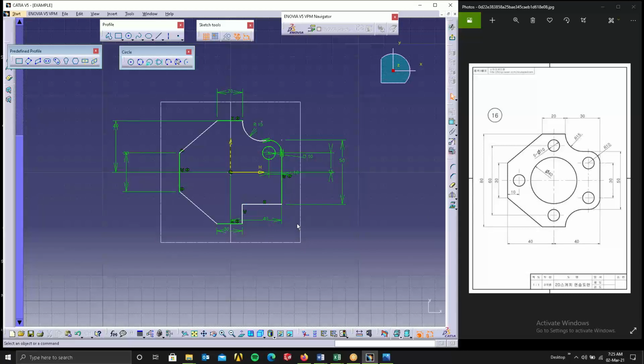Same thing we can do here also. Okay, so basically we do this with fillet command. So straight away we can just do it like this. Okay, this is how we do it. So I didn't want to use that tool, so we'll straight away give the value here 15, and here whatever value is there, that value we give here. Okay, this is how we do it. I just want to show you like without using one. So like this we can do it.